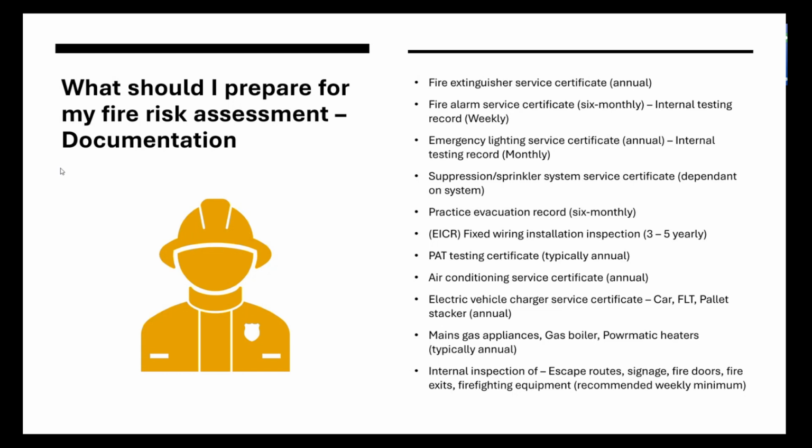Okay, as well as the fire alarm service certificate, which is on a 6-monthly basis by a competent fire safety technician or an electrician. That will be 6-monthly, should be recorded in the fire logbook as well, and should also provide you with a certificate. We will also need our own testing of the emergency lighting record and the fire alarm record available. Once again, fire logbooks are wonderful for recording all of this information, because you can get the vast majority of it all into a fire logbook.